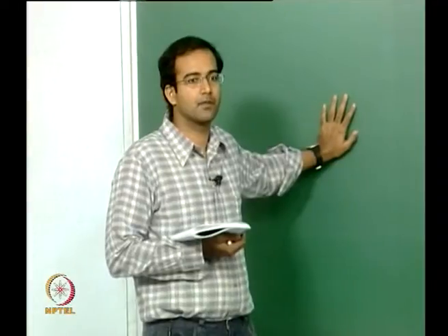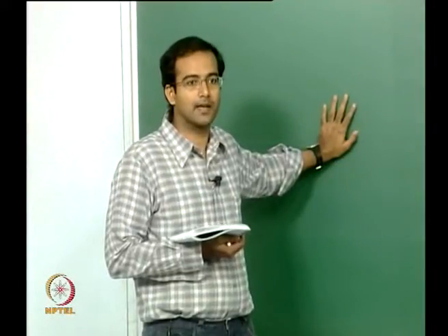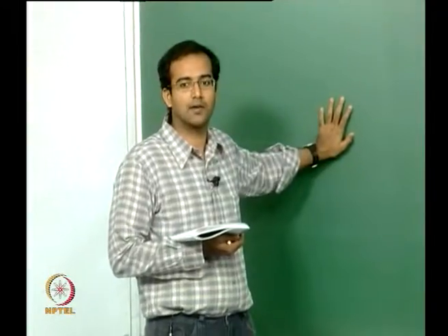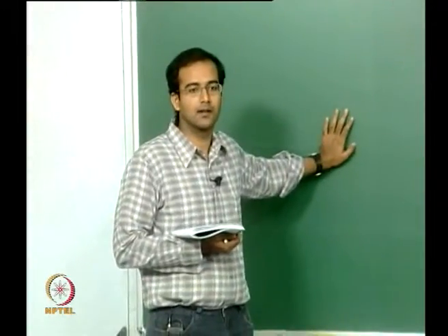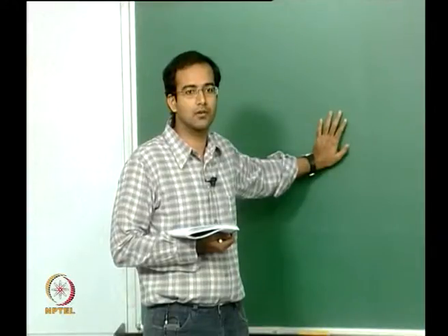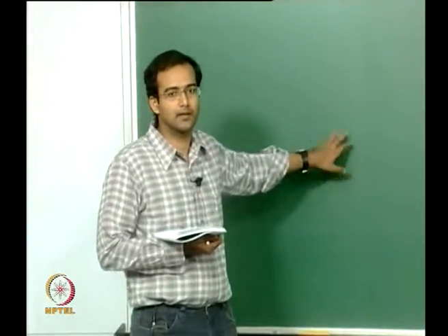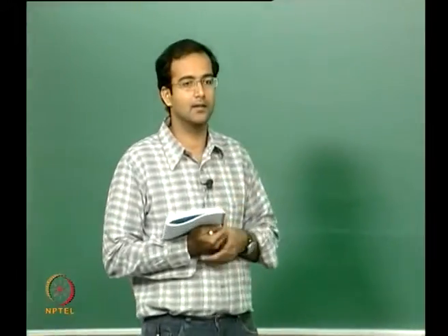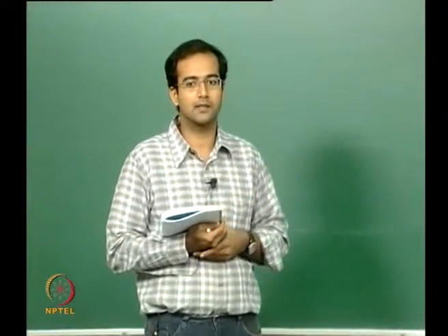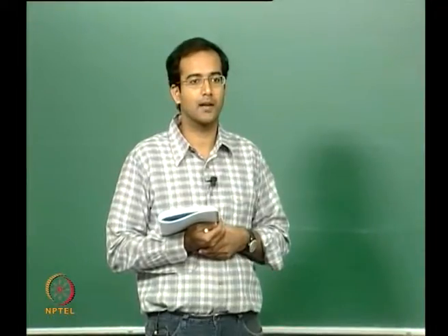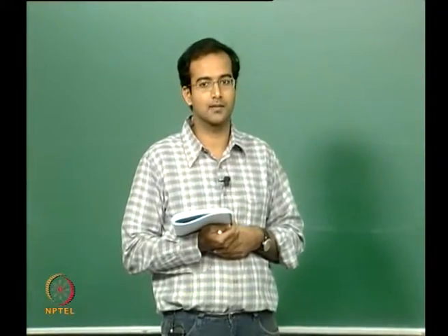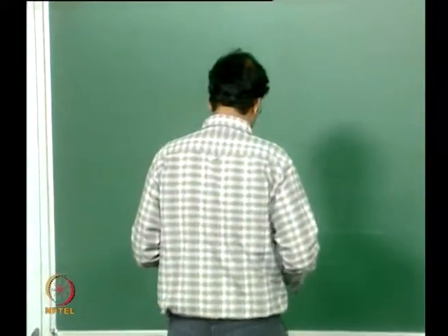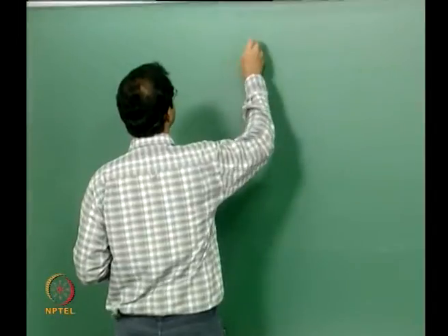We will look at the basic fully developed case first, where we can get the solution for velocity profiles very easily, and then gradually go to the case where we have heat transfer. We will look at different regions again. First we will start with the simplest case, both hydrodynamically and thermally fully developed. Before doing that, let me give you an overview of laminar internal forced convection.